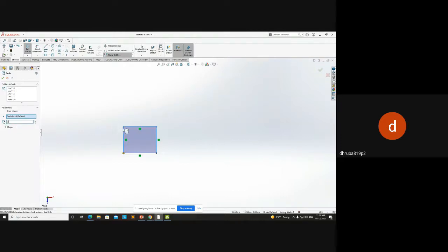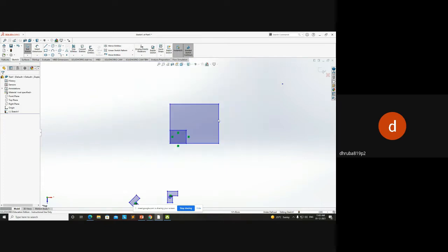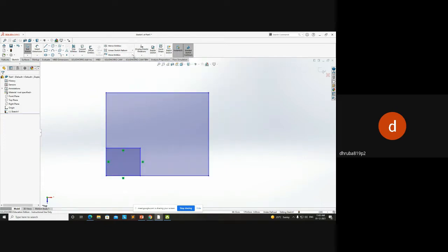That means I'll keep the original one, and create an enlarged version of this drawing. Just select 3 and press enter, and select copy. Here you can see, this was the base point, so the base point didn't move and the rest of the 3 points moved from their position. You have to see these things.